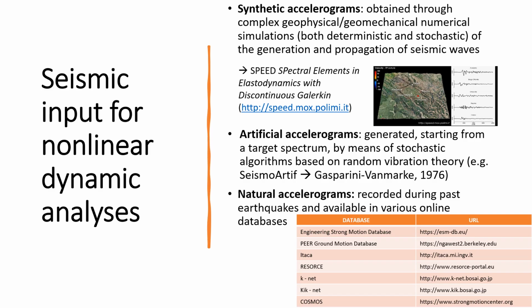In particular, we can use synthetic accelerograms, which are obtained through complex geophysical, geomechanical, numerical simulation, which can include both deterministic and stochastic procedures to simulate the fault ruptures and then the seismic wave propagation within the soil media to the surface where the building is located.